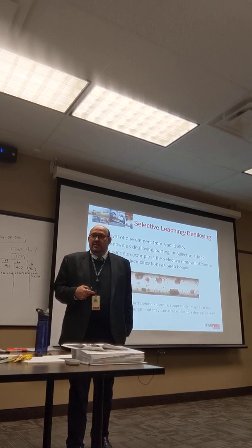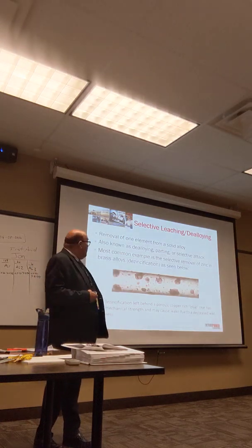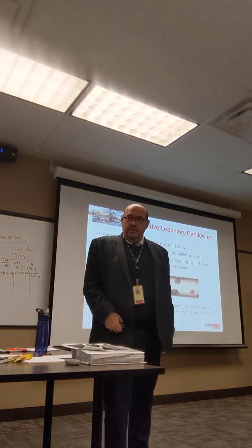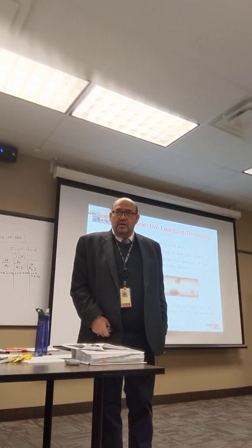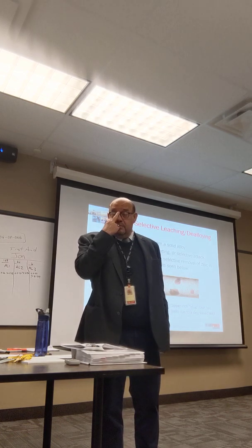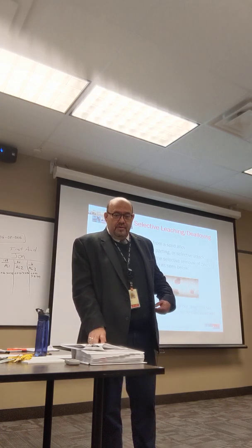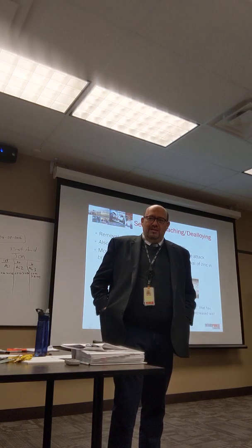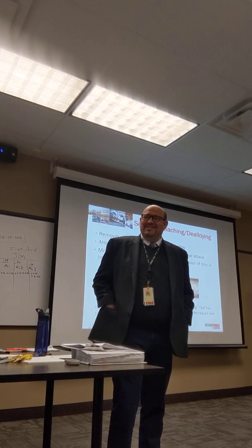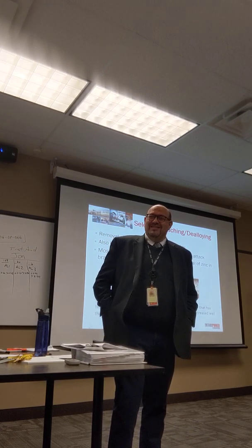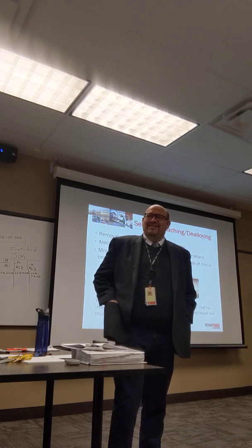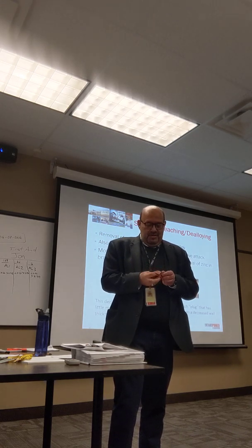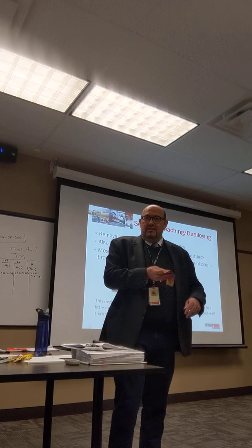Yeah. So another example is in Unit 4 at Pickering, de-alloying, the same kind of thing we have seen, and we plugged a lot of tubes in the heater area. Dezincification is common, and we concluded that it was caused by organic anions because of the high morpholine which we added. Yes. Now we have reduced the morpholine, which decomposes to organic anions, such as oxalate and acetate. So that's a good example which you have seen at Pickering Unit 4 and Unit 1 also.